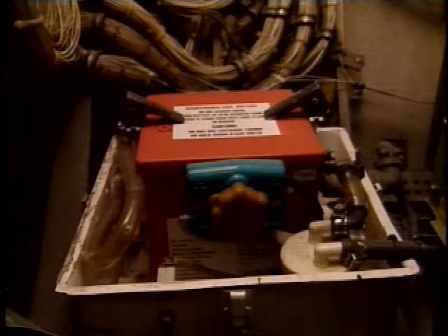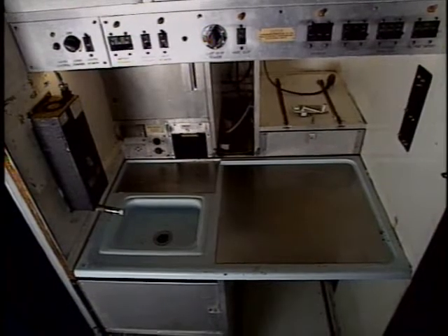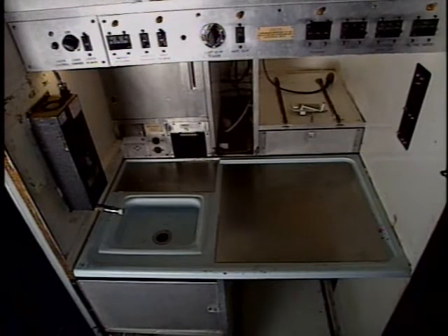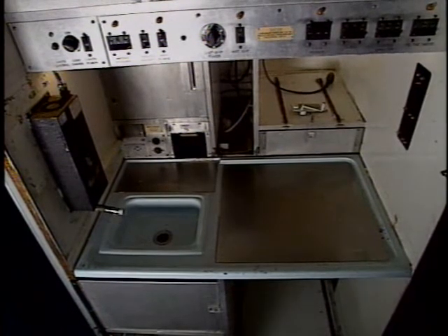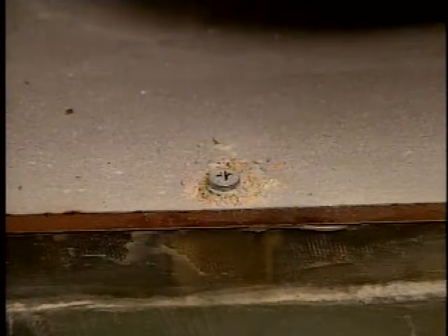Battery compartments offer a unique problem on the aircraft, despite the special paint coatings in these areas. Leakage of electrolytes from the battery cases or fumes from an overheated battery can cause rapid corrosion. Galleys, lavatories, and crew relief areas are extremely corrosive areas because of food spillage and urine spray. The latrine and crew areas should be inspected and cleaned after each flight.